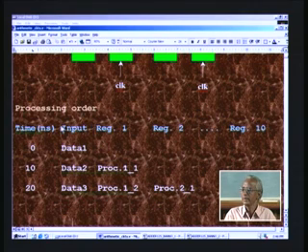Once you apply data 1, process 1 starts immediately, and after 10 nanoseconds that process will be complete, at the end of which we can register in reg 1 here, and that happens only then, because the clock will strike only after 10 nanoseconds.